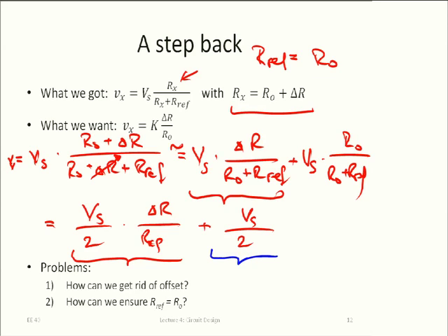Yeah. Stick an ideal voltage source of half the other source's voltage in the... Okay. We could use a voltage source to compensate it. All right. That's the first idea. An even simpler idea. Well, remember, we stick this into a microcontroller anyways. Then it's just going to be a digital number. That digital number has something added to it that is basically Vs over 2. We have to figure out how to get a voltage into a microcontroller, but let's not worry about that. So now, of course, we could use that microcontroller and tell it, whenever you get the result, you go and subtract this thing.